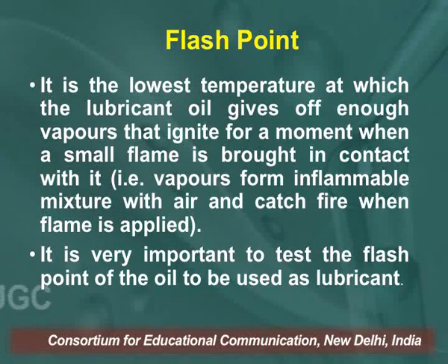Another property is flash point. It is the lowest temperature at which the lubricant oil gives off enough vapors that ignite for a moment when a small flame is brought in contact with it. That is, the vapors form an inflammable mixture with air and catch fire when flame is applied.